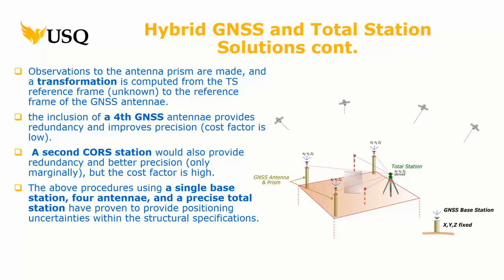Okay. So with the total station, you're going to observe to all the prisms, right? And we're already talking about frameworks here. So the prisms, which are part of the GNSS receivers, will have continual positions, right? Logged, whatever the logging rate is, but you can determine the logging rate. Let's presume it's near real time, right? You're going to measure usually robotically to all these points, and these are going to be our control points. They're the final measurement, right? But you tend to do it all at once. So it's all happening at the same time.